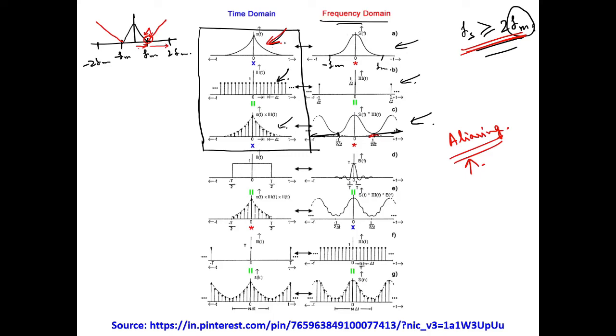The components being used will always be non-ideal in nature, and that might lead, not always, but might lead to some mixing of the high frequency component and the low frequency component. Even though aliasing-like mixing is happening, that is called frequency leaking, because it is due to the non-ideal parameters of your hardware.